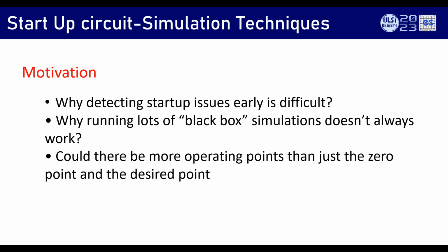Now, answering your question, how do you simulate a startup? I designed a startup. How do you know it is valid? How do you know that it will be robust? Detecting startup issues is difficult, and we need to run a lot of simulations. How can you be sure that there's only one 0 point and a reset point? There's only one operating point after the startup. How do you make sure that it is fine? These are the questions we need to answer with simulations. We need to prove it and say that, yeah, it works.